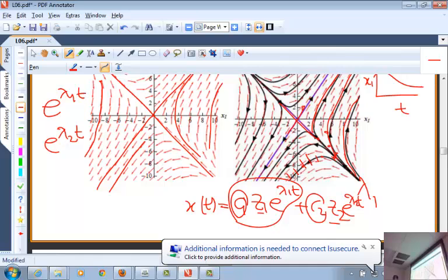There is a wonderful paper by Brooke Benjamin in the Journal of Fluid Mechanics called bifurcation theory. There he lays out, using topological theories, how you can detect unstable solutions. There are some indices that he counts that must remain invariant. Based on that, and he did some beautiful experiments on the Taylor-Couette flow, he found 21 different steady-state solutions for a particular problem. On the same operating condition, you observe a different number of cells. If anybody wants to take that as a project, it's a nice project to explore.